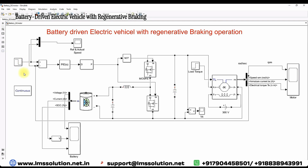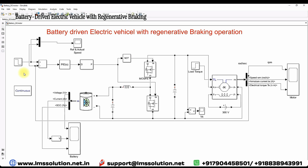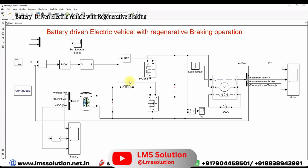For example, consider you drive the vehicle and increase the accelerator. The speed of the electric vehicle is going to increase, and you maintain around 80 km per hour. When you apply a sudden brake in the electric vehicle, there will be a torque in the negative direction, and that energy needs to be stored in the battery. That is possible by means of this bidirectional DC-DC converter arrangement. When we apply the brake, whatever energy is stored in that machine is returned back to the battery via this DC-DC converter.